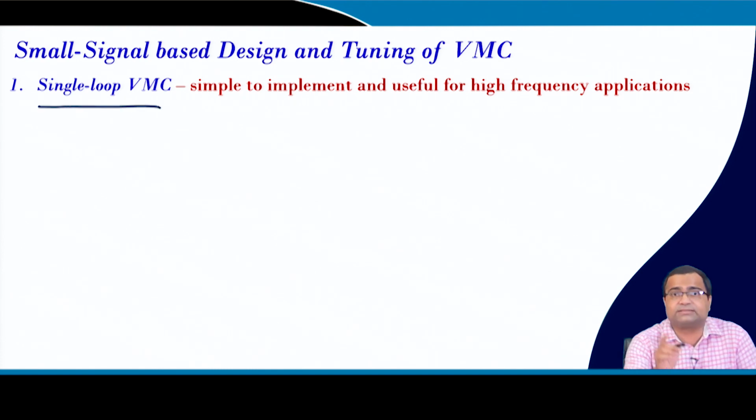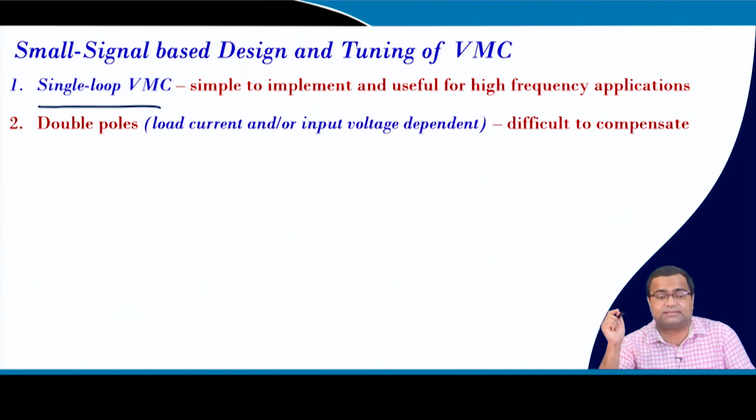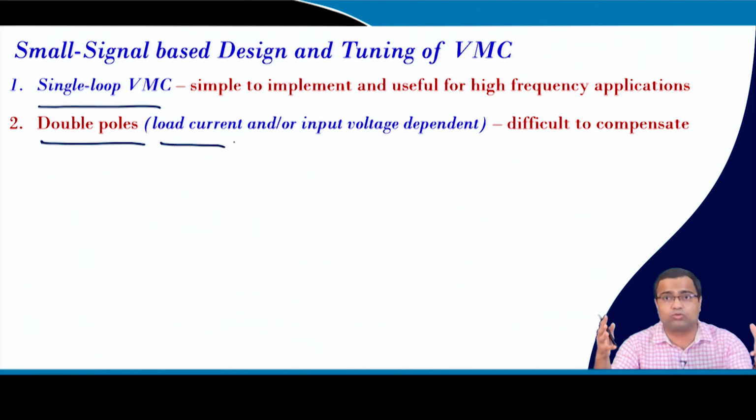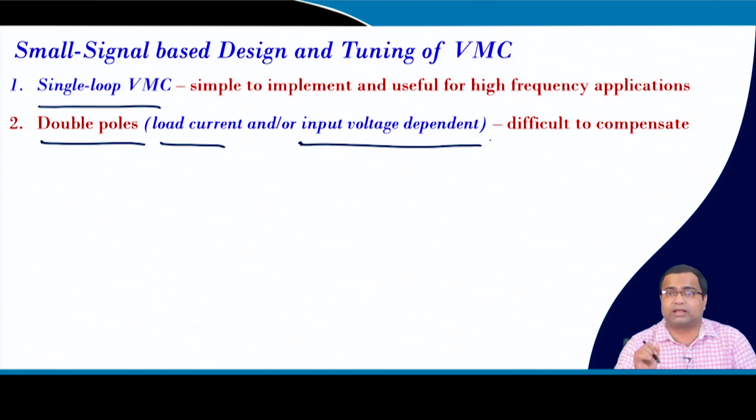and the voltage mode control is a single loop control. It is very simple to implement and useful for high frequency application, because there is no current sensing. But the problem is the double pole, and the double poles are often a function of load resistance or the load current, and in case of boost converter and buck boost converter, it is also a function of input voltage along with the load current,